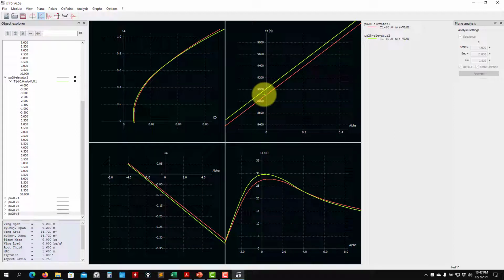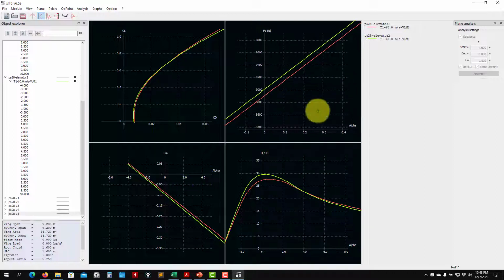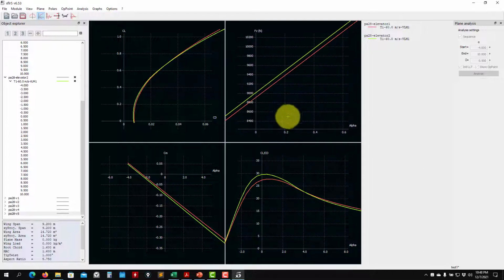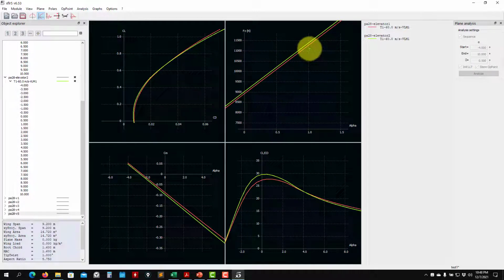Now it is outside that effect, so you have an influence. Okay, and everything is due to that downwash that the tail is seeing. But still, it's not ideal. I would like to trim this airplane about 1 degree, or let's say 0.5 degrees will be my optimal one. But to have it balanced, I need to go something about 0.3. So this is now good. I need to add in the elevator, change the angle. So our next modification is that one.